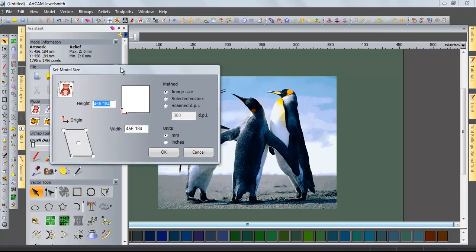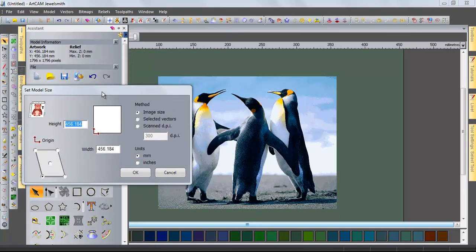The numbers set here are the overall size of our page. It shows us that it is 450 by 450. And while our page is here, it shows us that our origin point is in the lower left corner. From here we can make changes related to the origin point. To match the starting point of our machine, we can determine our origin point here.